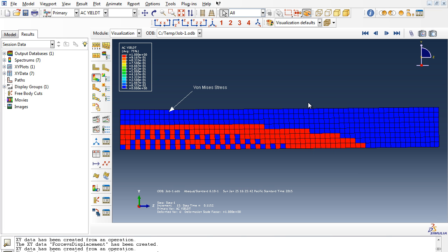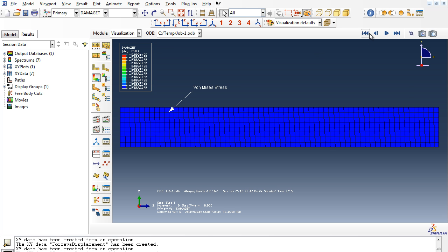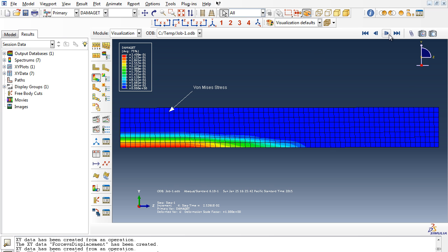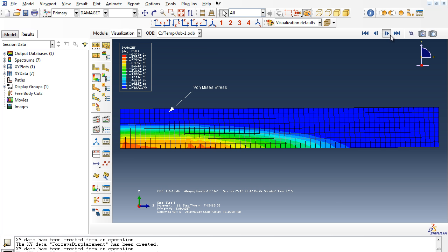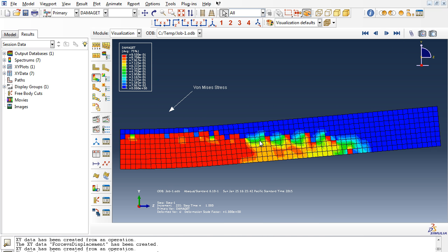If you decrease it like we did in the previous video, where we went with 1/4 inch, it had been like 40 minutes and it was only 10% complete. So if you want to be that accurate, then you can let it run overnight, and maybe by the time you wake up the next day, the analysis will be complete. So that's the active yield, and then the tension damage. You can see tension damage on the concrete as it progresses. The full cycle. All these have it has failed.